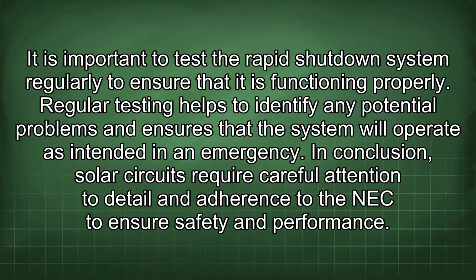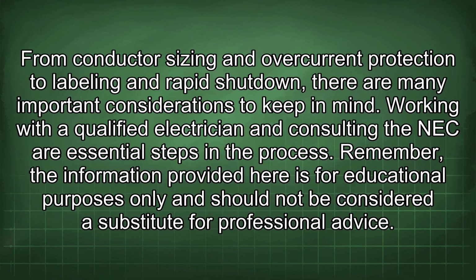In conclusion, solar circuits require careful attention to detail and adherence to the NEC to ensure safety and performance. From conductor sizing and overcurrent protection to labeling and rapid shutdown, there are many important considerations to keep in mind. Working with a qualified electrician and consulting the NEC are essential steps in the process. Remember, the information provided here is for educational purposes only and should not be considered a substitute for professional advice.